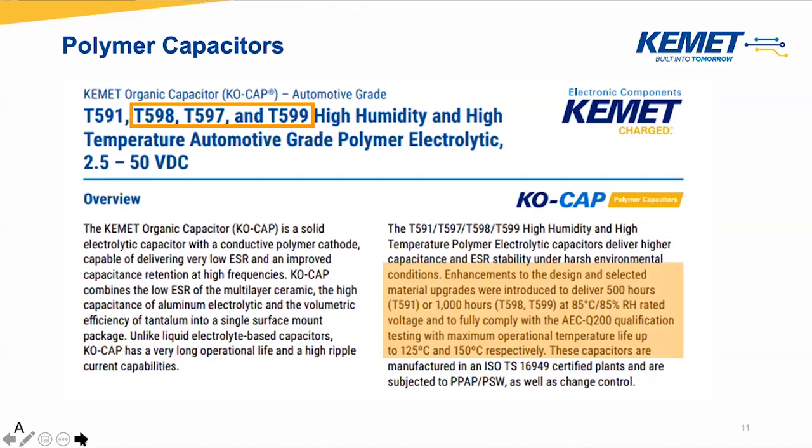That means a drop-in replacement where you can substitute 0805 and 1206 capacitors with the polymer capacitors, high capacitance. High capacitance means 10 microfarad and up. All these parts are automotive qualified, AEC-Q200 applied, and we have done a lot of tests to prove the reliability and lifetime, and we can really provide you with data on that.